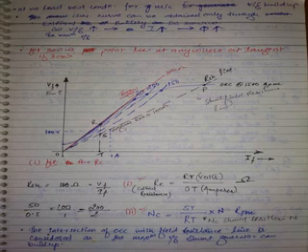Now let us consider OCC plotted for 1000 RPM. Where is point P? Further decreased. Further decreased. Now let us say some speed which is a critical value. What is this blue line? It is the original shunt field resistance line. Yes or no? Now, we don't know the speed, let us say NC, at which the original shunt field resistance line is making a tangent to OCC.